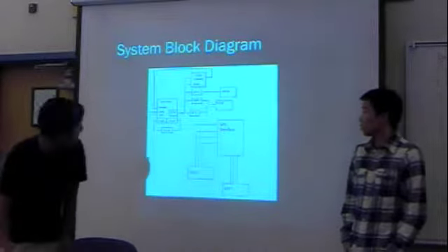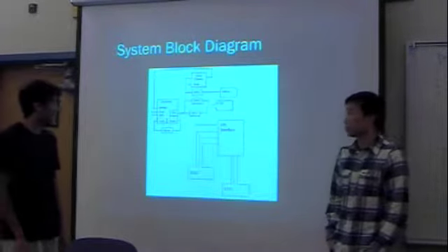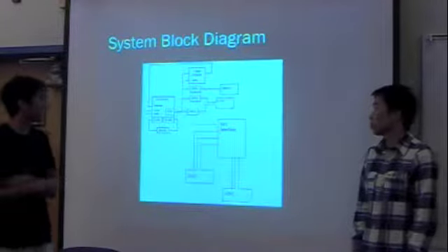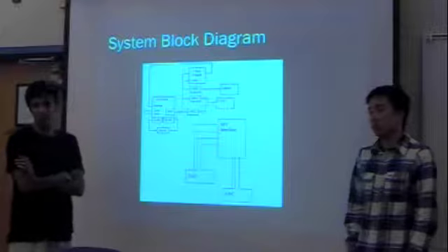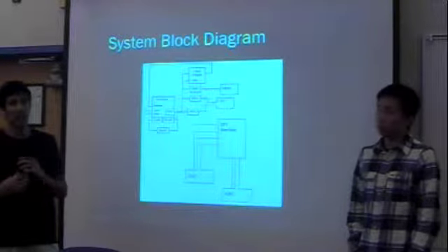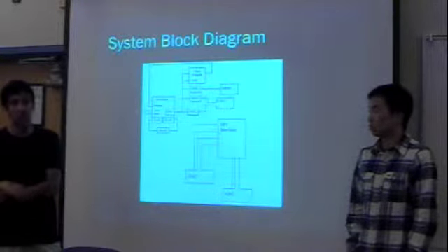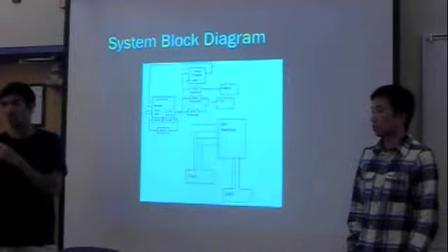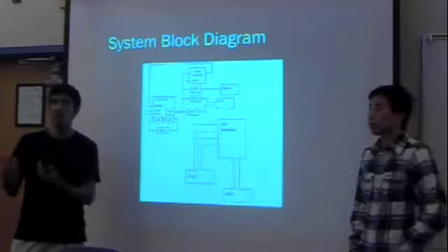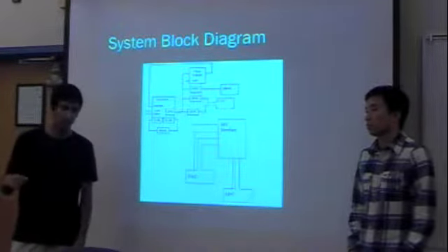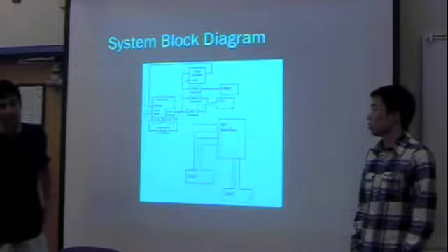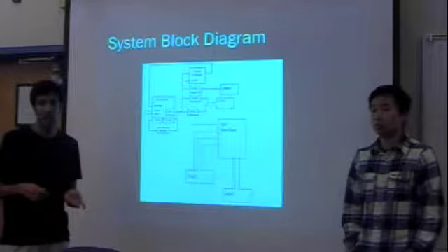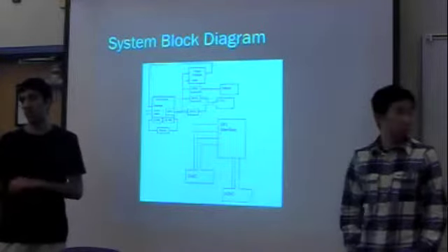So for the hardware part of this, it's pretty much the same thing as the temperature sensor with the DAC and the ADC. The guitar in would come in from a gain offset circuit, so that would be an op amp that just boosted the gain of the guitar to a range of 3.3 volts peak to peak, and then that ran through an offset circuit to get the full range of the ADC. So the guitar was inputted through there, and then it went into the Nexus board. All the DSP was done in there, and then as of now, it's output directly through the DAC.